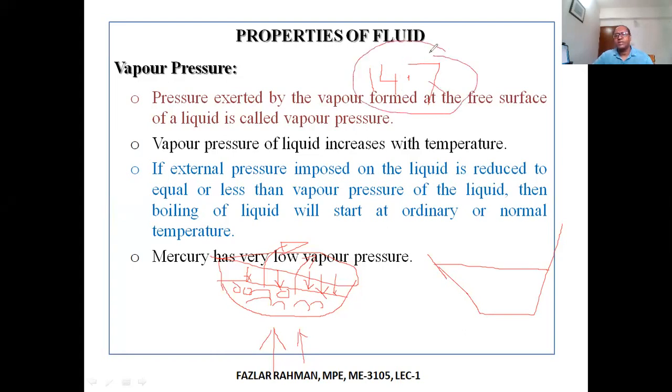But at the top of the hill you might get, for example, 13.7 psi. That means at the top the surface pressure is less, right? So your water will boil at a lower temperature and also quickly, because at the top surface it is feeling less resistance because pressure is less.